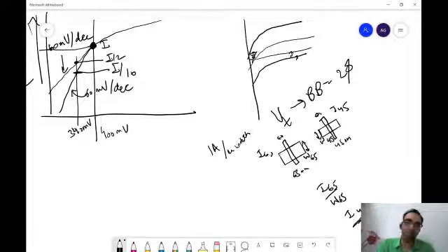But that is where I'm saying, because we are going to complex device topologies, it might not be the most appropriate or sustainable way to handle it in very advanced technologies. So I do not know. But for all practical purposes, you can assume that constant current per micron width is the definition of VT.